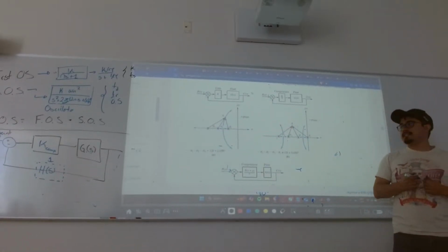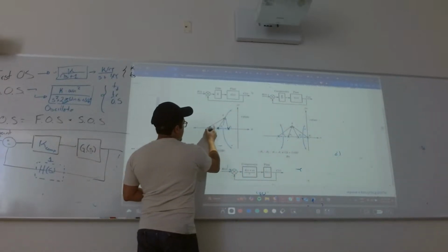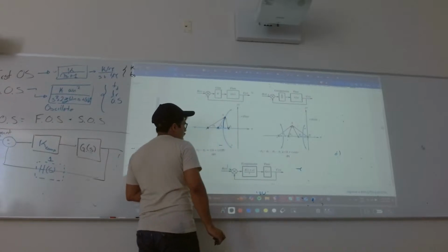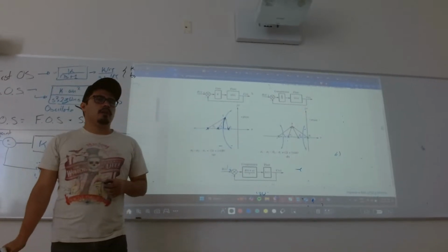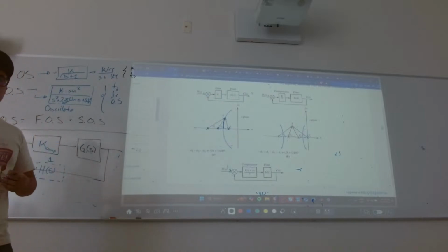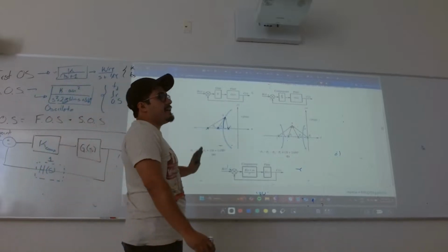It's a third order system with our poles originally at these points, and I chose a case so that my system is performing like this. Right? But that has a steady state error that I wanted to improve. Therefore, I need an integral. And he says, okay, just have an integral.